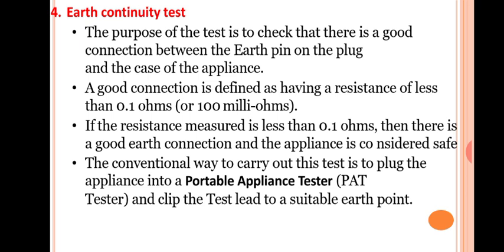To avoid that, you should see that earth continuity is there. Whatever leakage current is there, it will go to the earth. It will not break.